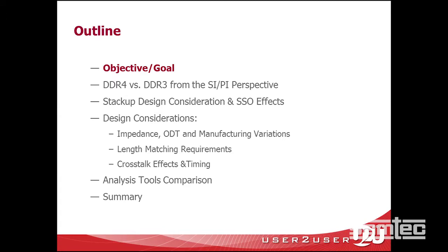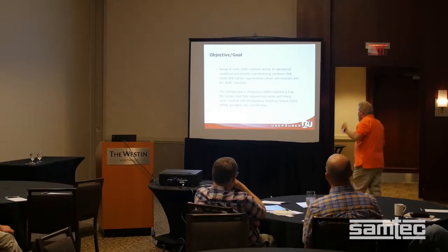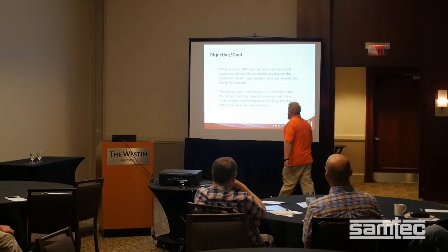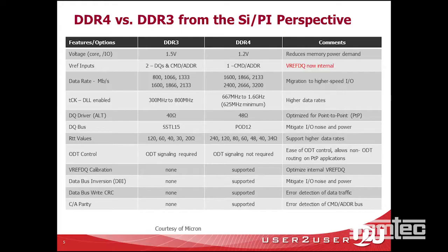What we want to do is look at the difference between DDR3 and DDR4, because there are some differences. I want to look at some stack-up considerations. So the big thing is the company we were doing this for wanted us to do, of course, all manufacturing variations, best case, worst case, board stack up, impedance changes, everything, because this was going to go into a heavy-duty situation. So we wanted to make sure of that, and we had to do it with crosstalk and simultaneous switching outputs also.